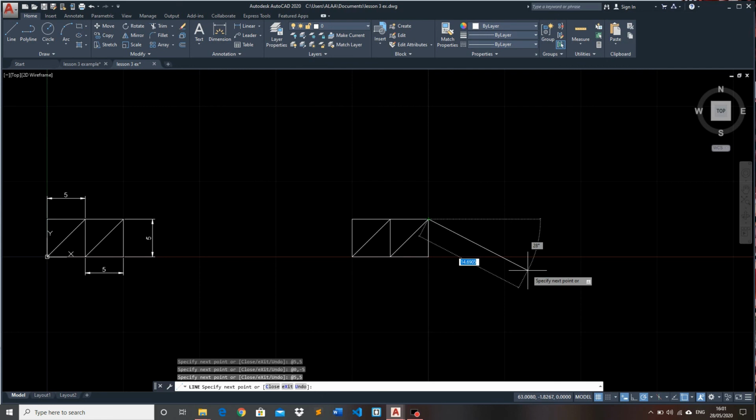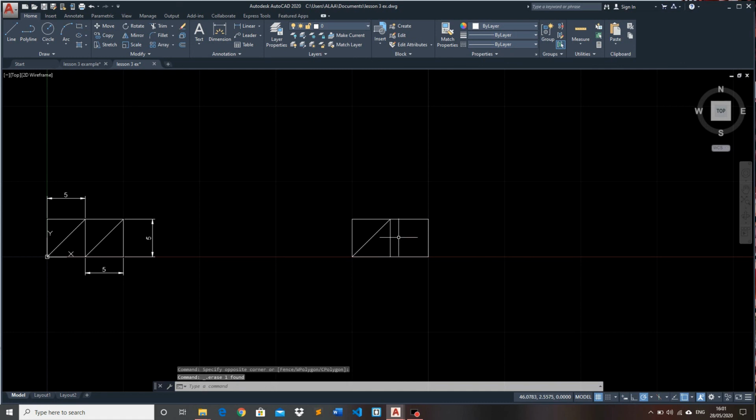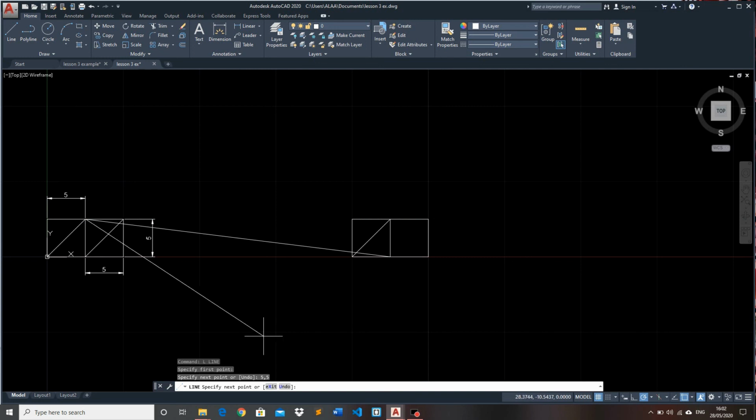Okay, like this, and here I can just directly use comma, just like I said, 5, comma 5, because the dynamic input is on. If I turn off this thing, let me draw this again. I will say L, then I will say like this. If I click 5, comma 5, sorry, you can notice that here I don't have any numbers. The numbers are in the command window. So I will click 5, 5, and it will draw 5, 5, which is this point, as it's now using what we call the absolute coordinate system. So let me click Ctrl Z and let me complete this thing.